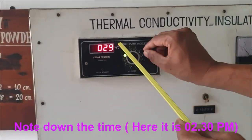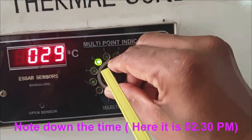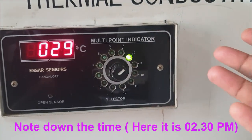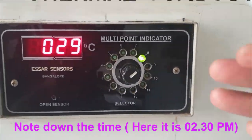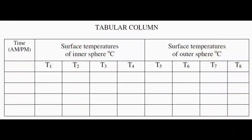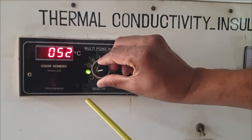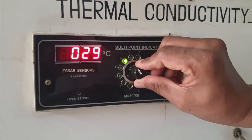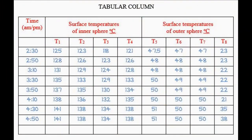Now for doing the experiment, we need to note the temperatures of each of these points at different intervals of time. We put the time in the left column and all the temperatures in the other columns, and we will find that with time there will not be much change, and that is the point where it has reached steady state. We take these temperatures and apply them in the equation to find out the thermal conductivity.